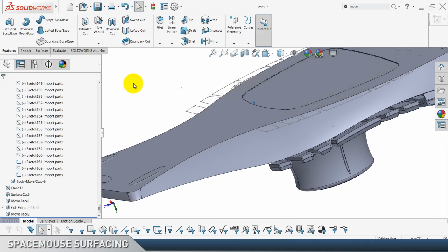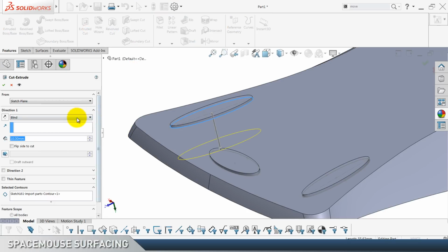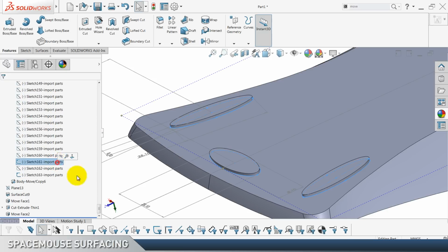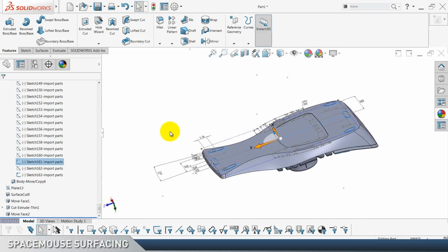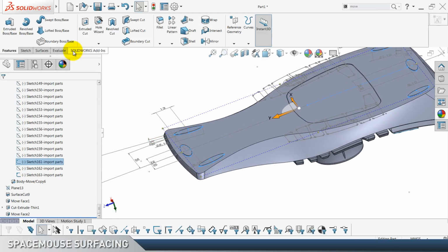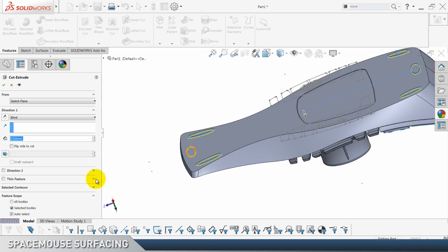and we are gonna use this sketch, extruded cut. We actually want, it's this one, we want all these, so press here on sketch, don't press that one piece of sketch just like I did. So again, extruded cut 0.5, and this is direction.